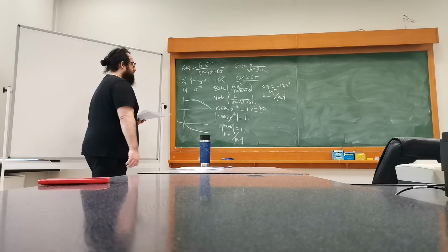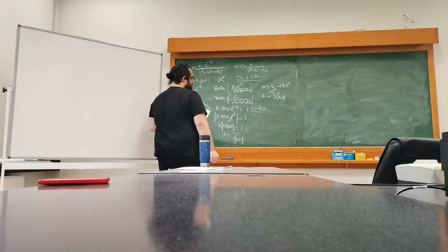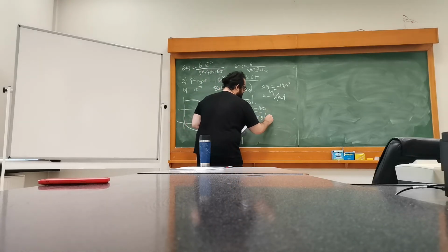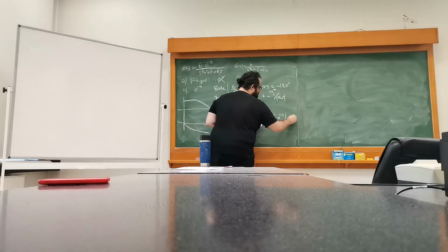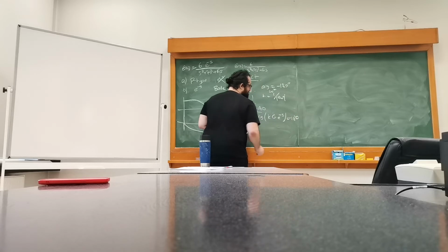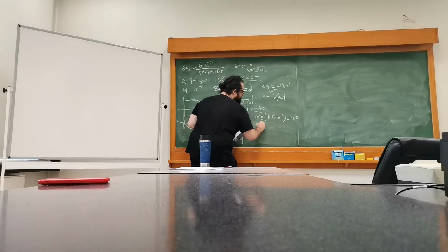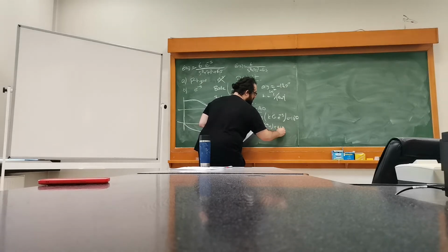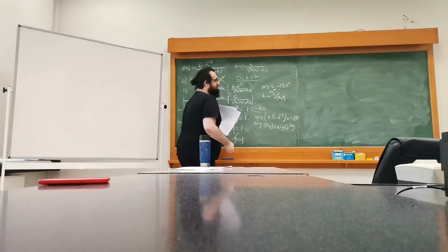But the problem is with the argument here, the phase condition, because the argument of k times G times e to the power of minus s should be equal to negative 180 degrees. The problem with that is that the argument of k, if k is positive, is 0, so the argument of G(jω) plus the argument of e to the power of minus jω should be equal to minus 180 degrees.